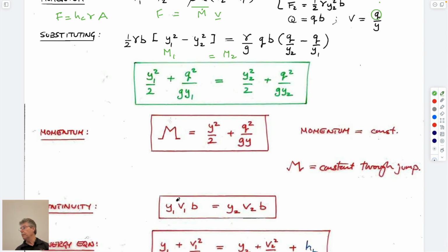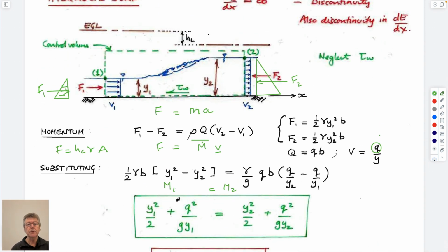And we know that we conserve momentum when we go from upstream to downstream. We don't necessarily conserve energy because we might have energy losses in the system. And so I guess I should talk about the fact that what we're doing is we're going from upstream to downstream. We have a depth upstream and a depth downstream. From the energy grade line, which would be the depth plus, I guess this would be v squared over 2g, right? To the same down here. We have a change in energy because we have a loss in the system. We have these big vortices that are developing, which eat up all the energy in the system as we're flowing downstream by recirculating the water.